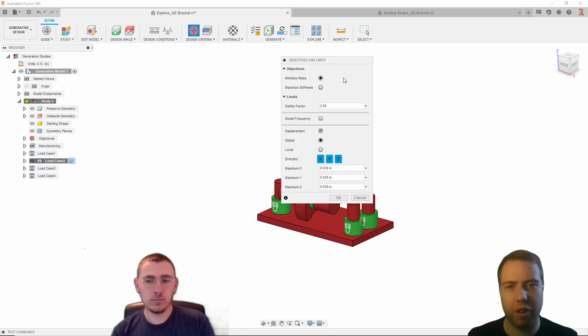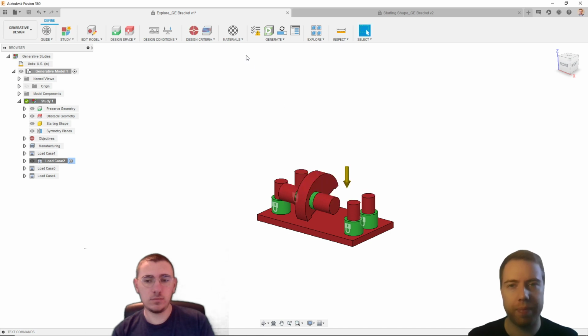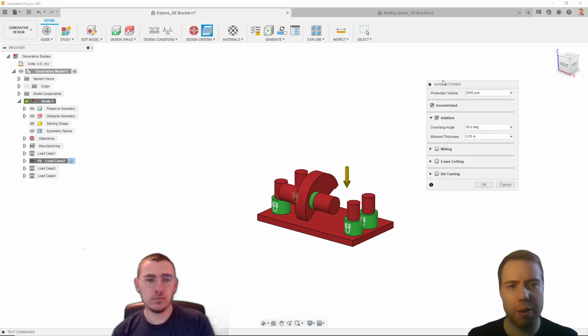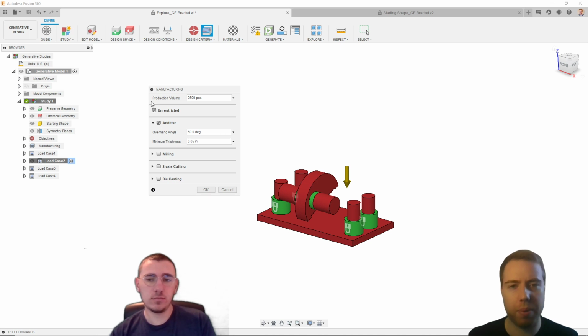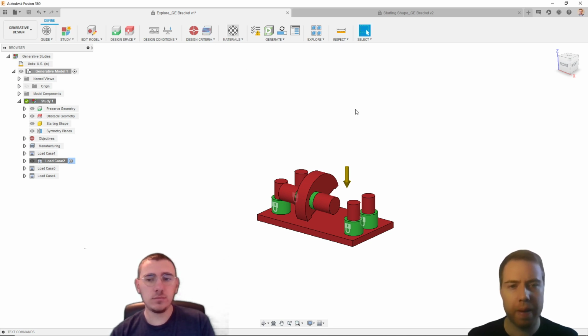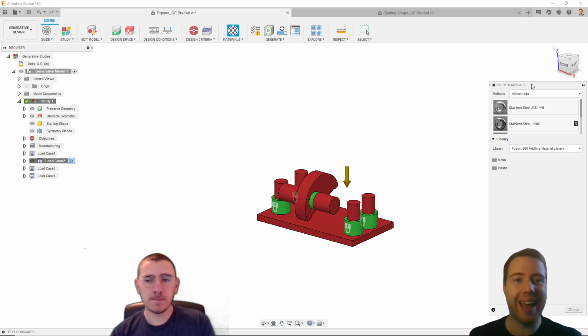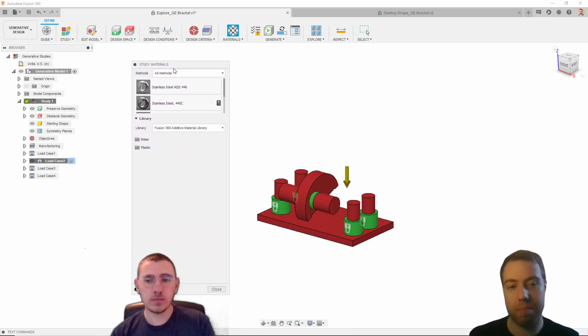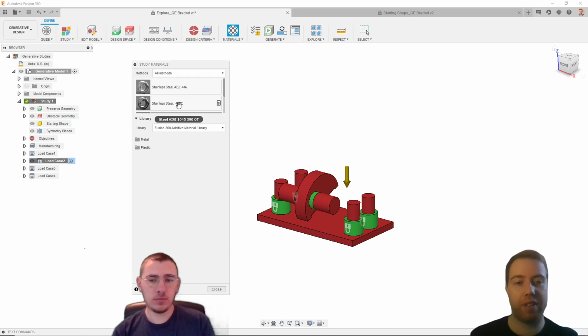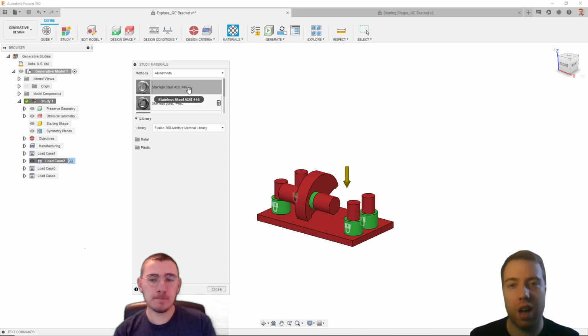We can also see the objectives that we used. So in this case we ran minimize mass with a safety factor of 2, and a couple of different manufacturing methods. We've only really explored 2 in this case, the additive constraints and the unrestricted outcomes. And the fewer manufacturing constraints that we decide to explore, that's going to affect the number of results that we get out the other side. So by including additional manufacturing constraints, we could have actually got many more different possible outcomes.